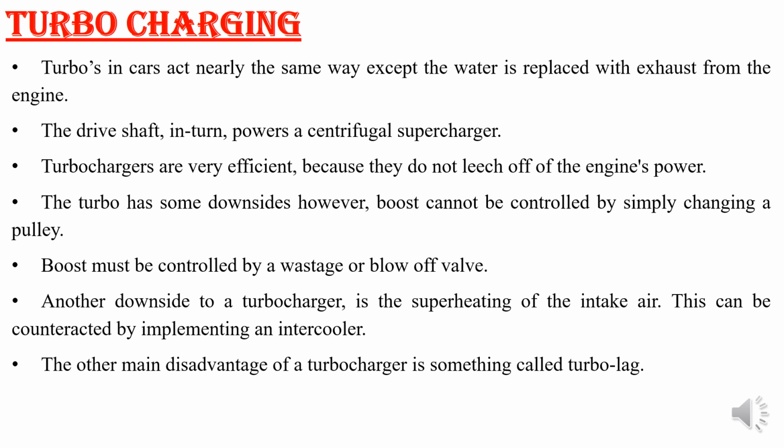One of the disadvantages in your turbocharger is that there are two components: one is the turbine, and one is the compressor, which are held together on a common shaft. Because the turbine works in a high temperature region, heat will be transferred from the turbine to the compressor through that shaft.